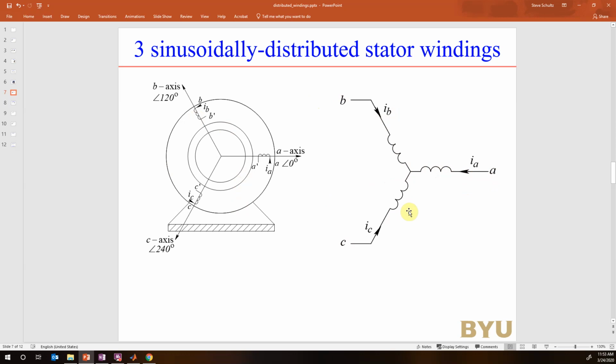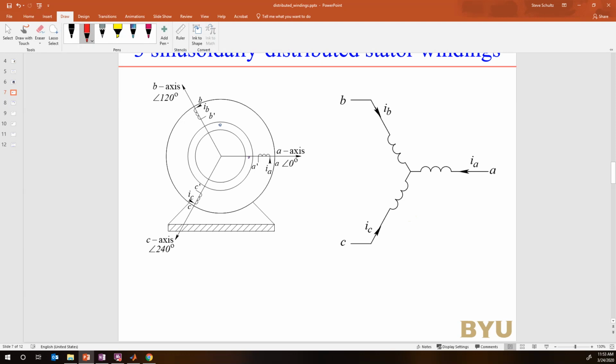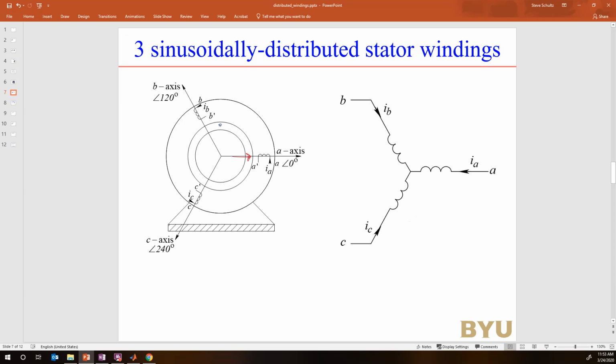So what we see here is, remember, the sinusoidally varying windings that had a low density here and a high density there is going to create a magnetic field that's in this direction. So that gets modeled by this winding. You see this winding has a magnetic vector that's going to be going that direction. We're going to create another one that has its magnetic field line going up this direction. So that's modeled by this one.